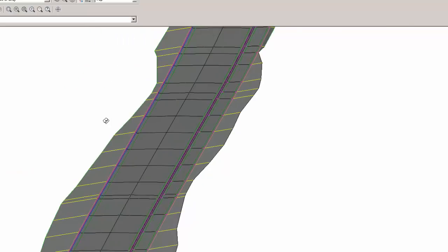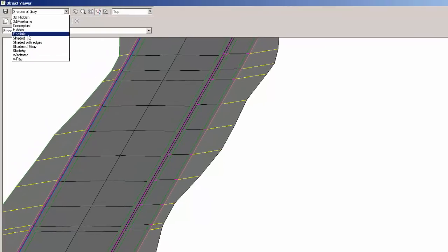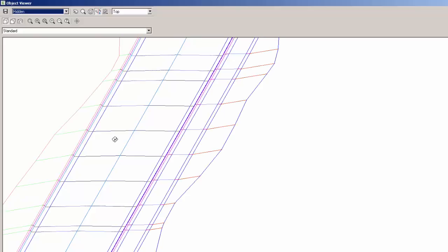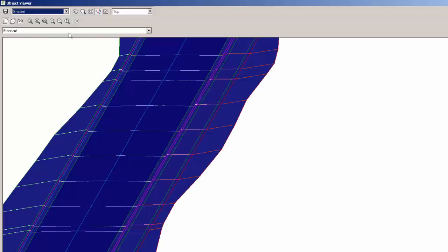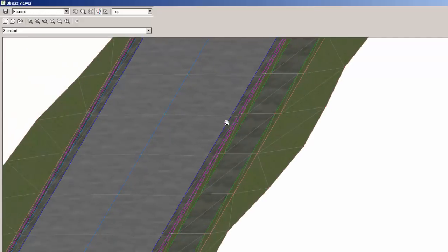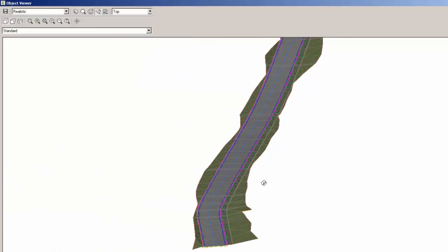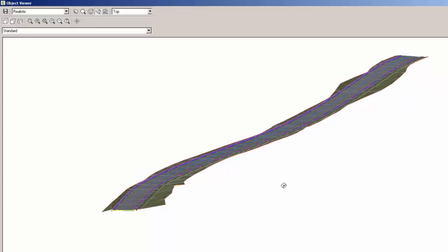roadway here. So here you can see the roadway, here's the curb, and then here is the daylighting. On the right side we've got a curb, and then we've got grass, a sidewalk, grass, and a daylight as well. If we turn it to the realistic, you actually can get a little better view of what we have going on here. So you can see the roadway, the curbs, the grass, the sidewalk, and if we zoom out and we kind of pan around, everything looks pretty good.